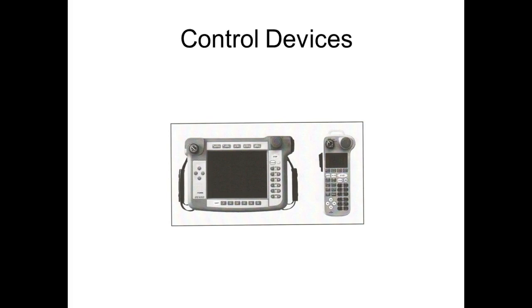Continuous path robots, you can literally go out there and grab that robot and put it in what we call a floating situation. You grab that robot and move it through the path you want it to remember, and it records that. Those are probably maybe 10% of the robots out there. It takes a lot of money. It takes a very complicated controller to be able to do that.